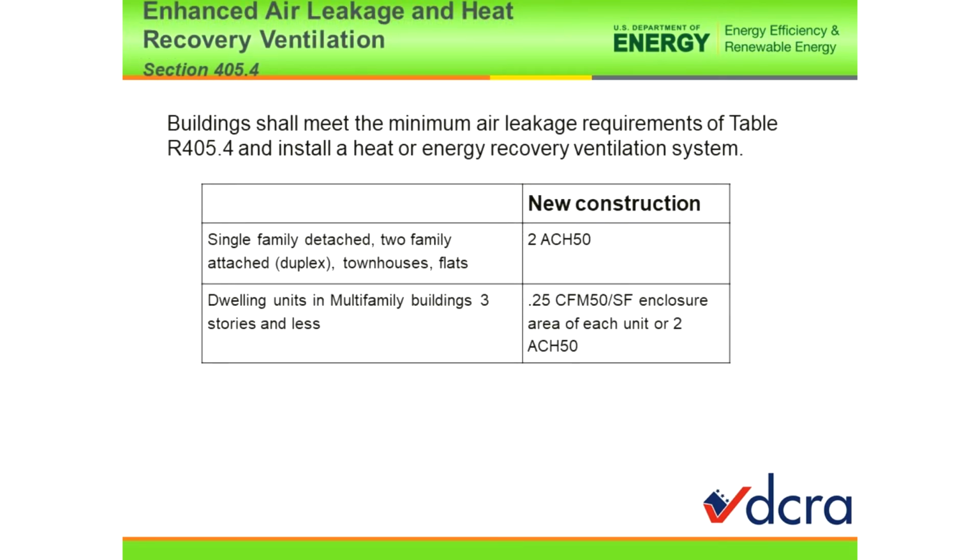Air leakage, enhanced air leakage and heat recovery for the enhanced package. Now, from 3 air changes, you're saying that you're going to take it down to 2 air changes. Boy, that's a tough one, but if you do that, you are really going to have to now take care of that mechanical ventilation I was talking about earlier, okay? It's really important then. So if you choose this particular way to go, you better believe you're going to be bringing in mechanical ventilation, and it's going to have the proper control methods, all right?